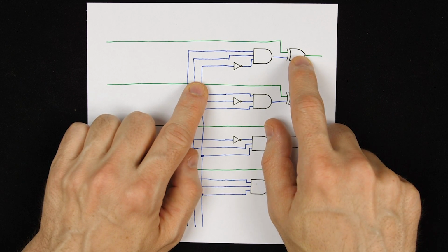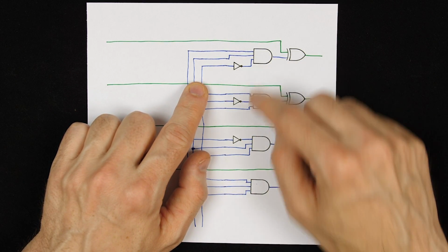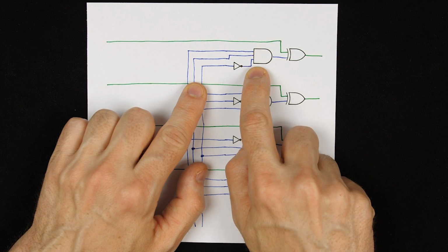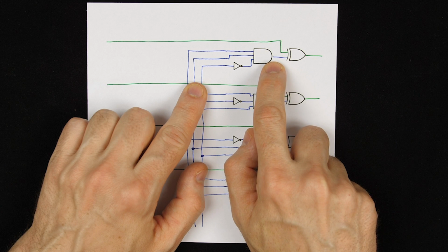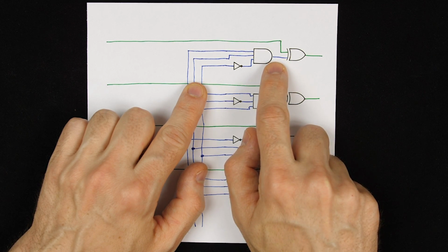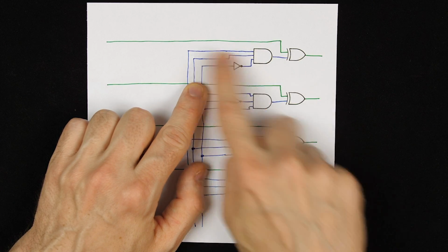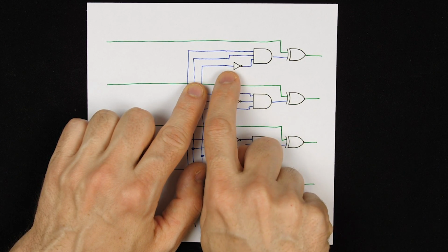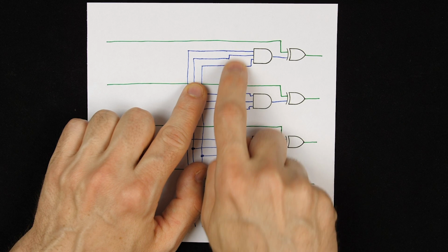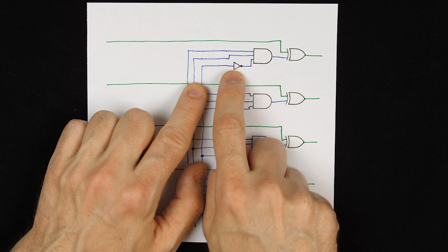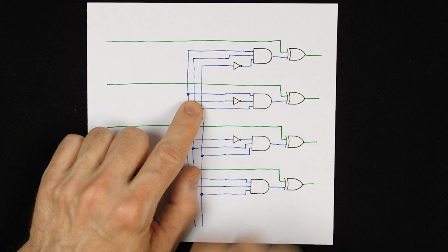And the way to do that is with a simple decoder circuit, and that's what these AND gates are. So these are AND gates that say, okay, if all 3 inputs are 1s, then the output is going to be a 1, otherwise the output's a 0. So if all 3 of these inputs are a 1, then it flips this bit, otherwise it doesn't flip the bit. And then we can position an inverter on whichever inputs we want to be able to use this AND gate to select a particular value from these 3 bits.